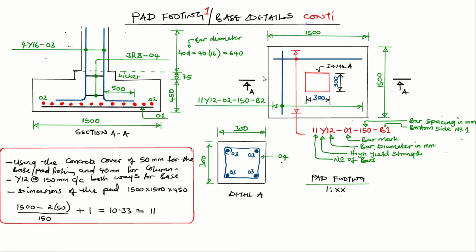So when you cut, this becomes your section called section what? AA. So for example here, because we've given it names A and A here, and we're cutting at the middle. And remember that your section must always cut through this column that is on top of your base. It must always cut through this column. Then once you've done all this, you're just supposed to give it a name as what? Plan view. Once you do that for your base, you would have been done.